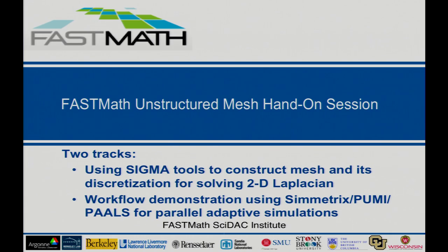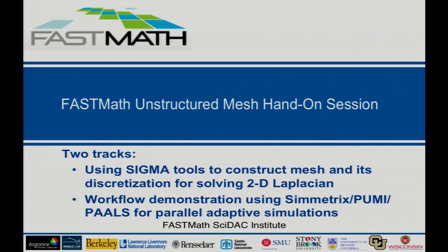So this is just an introduction to the hands-on session. We have two separate streams. One is with the Sigma tools. They are basically two different workflows. With the Sigma tools, you start off with the API descriptions. We go through the process of loading the mesh, creating the mesh, and then using a Laplacian solver on the mesh that you generated. While with the PUMI Simmetrix PALS workflow, you start off with a larger application, and then we'll break it down and describe the details involved.